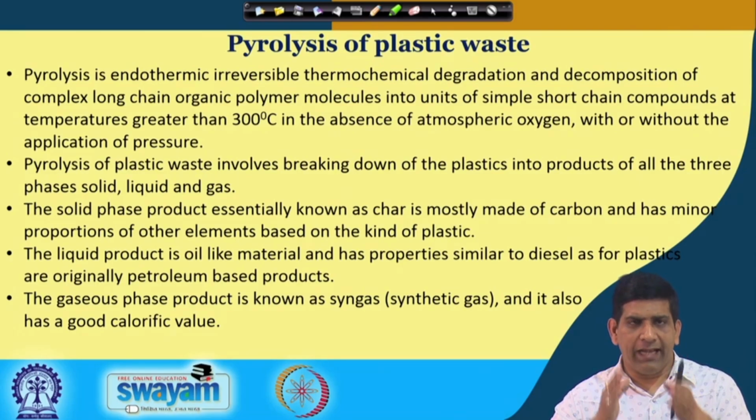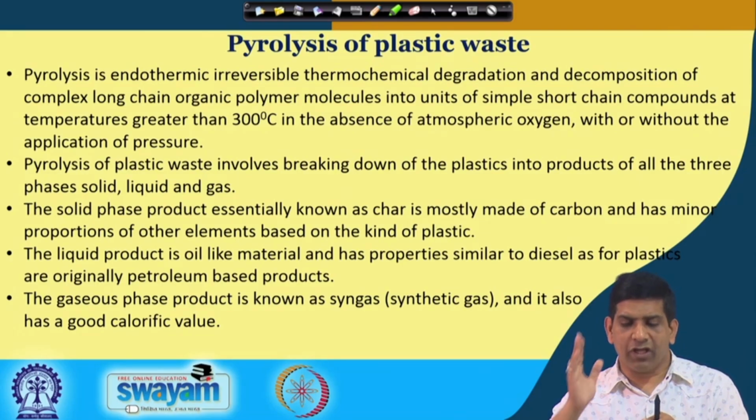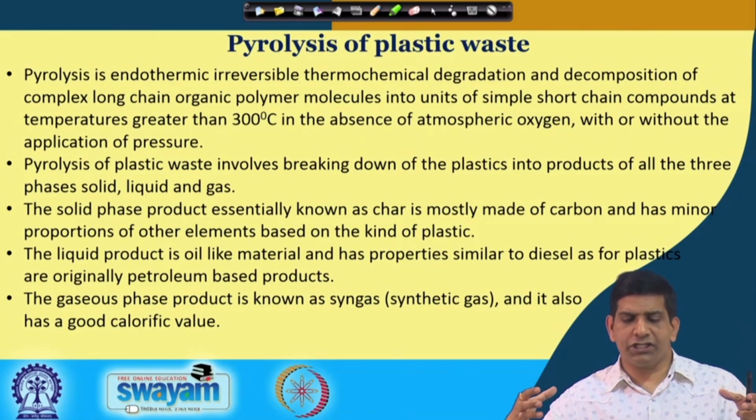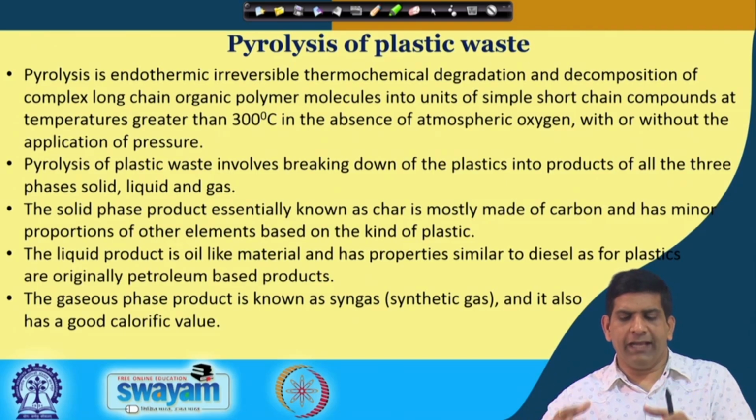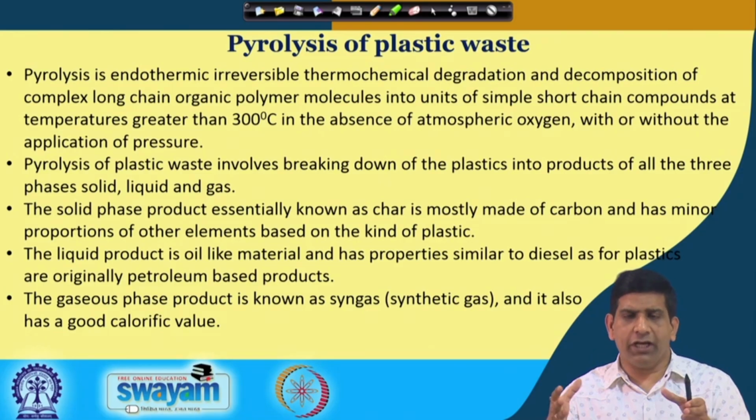So you are doing an endothermic, irreversible thermochemical degradation and decomposition of complex long chain organic polymer molecules, because that's what you have in plastic. And then you convert that into units of simple short chain compounds at temperature greater than 300 in the absence of oxygen, with and without application of pressure.